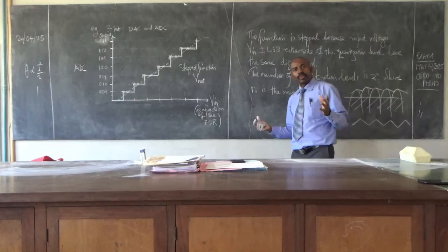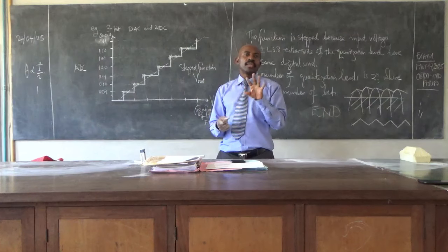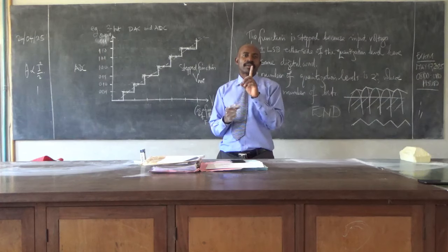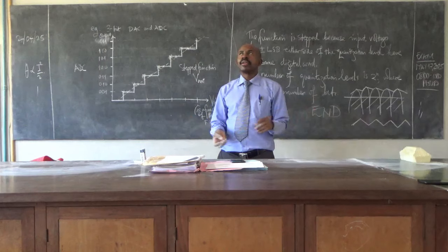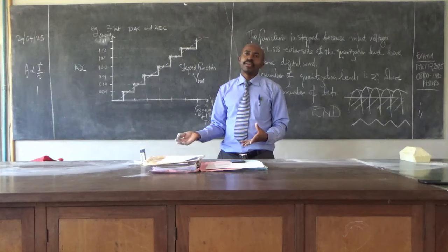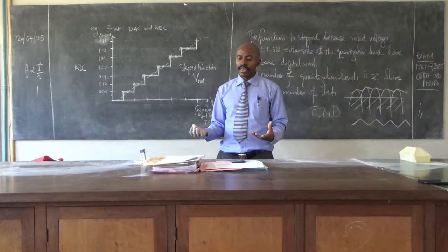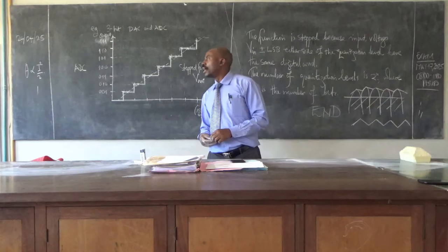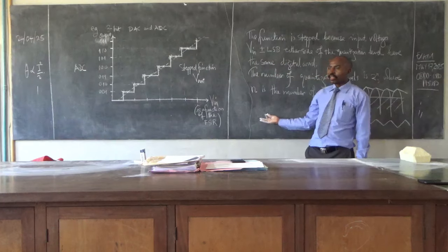And then you were able to appreciate that the amber, the yellow one on the road, is the monostable, which has one stable state, so it comes on very fast and goes away. And then flip-flops, we did JK, RS, set reset, and came to conversion.